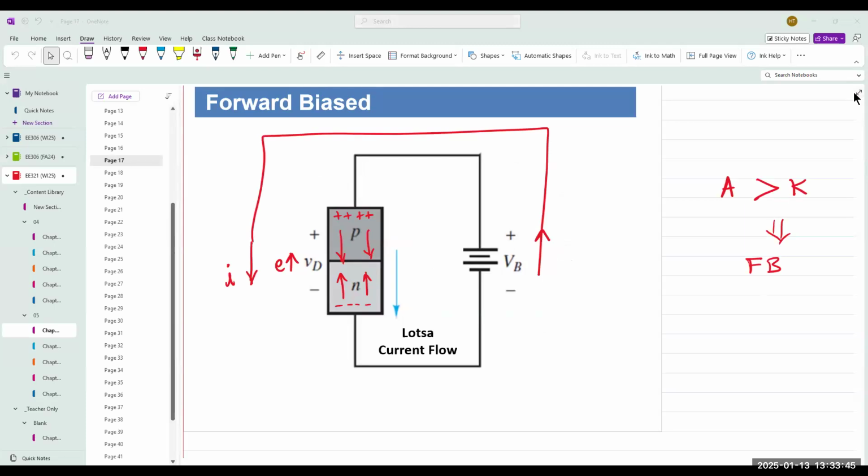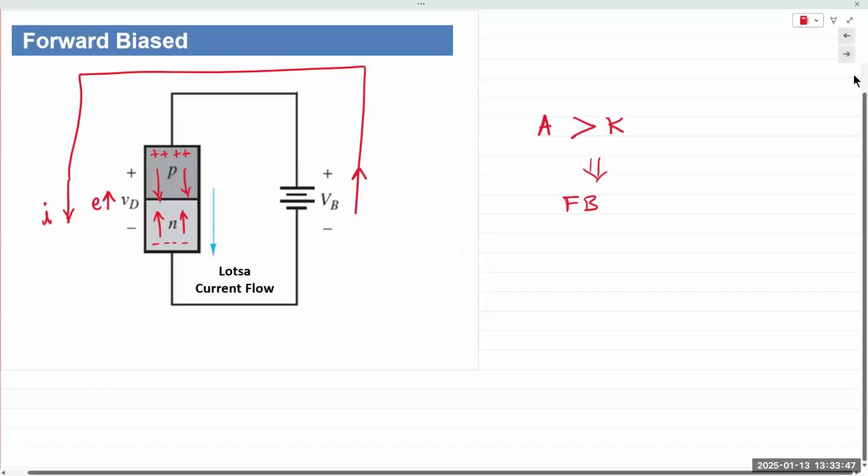All right. So we looked at p-type semiconductors, n-type semiconductors, and then we created a p-n junction diode using p and n-type materials, right? So when we bring them in close proximity, or when we fabricate them with close proximity, at the junction of the p and n-type material, the electrons and the holes recombine. Recombination takes place, takes out two of the charge carriers. Hence, there's a region right there at the junction that's devoid of all charge carriers or all charges. Hence the name depletion region.